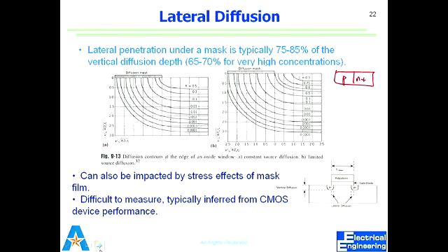So we see that junction depths have to be made smaller. But when they become closer, there is lateral diffusion also, which causes the space charge region, or depletion region, of source and drain to overlap. When they overlap, it means we are already making the connection between source and drain, already causing them to short, which means essentially we are losing control over the gate. Does it make sense? Let me draw it.